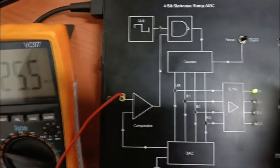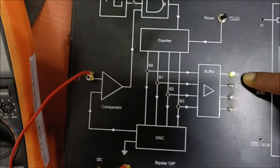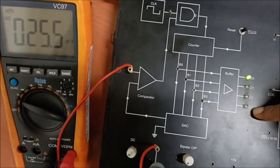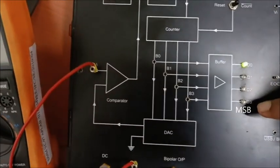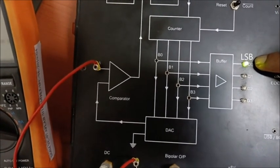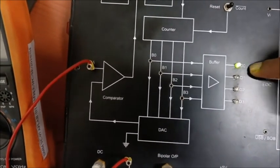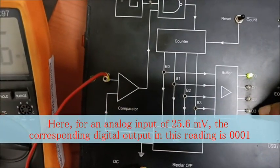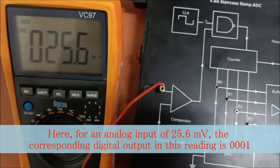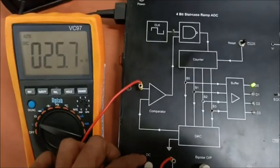So here we can see the first LED, the D0 input has turned on. So this D0 is now switched to 1, and this D1, D2, D3 all are 0. 0, 0, 0, 1. This D3 is MSB, most significant bit, and this D0 is LSB, least significant bit. So here we can consider this output as 0, 0, 0, 1. So corresponding to this 0, 0, 0, 1 output, we have supplied the input of 25.6, almost 25.6 millivolts. Here you can see in the multimeter.